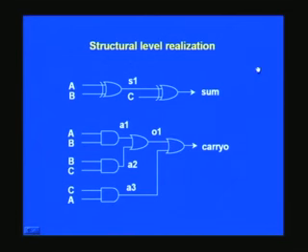And the very same full adder depicted using gates is this, with a view to primitive gate implementation, it has been put in this fashion. Note that S1 is an intermediate signal which we will be using, and similarly A1 through A3 are intermediate ANDed operations here, and you can OR these, and once again O1 is an intermediate signal you will be using, and the final results are sum and carry.